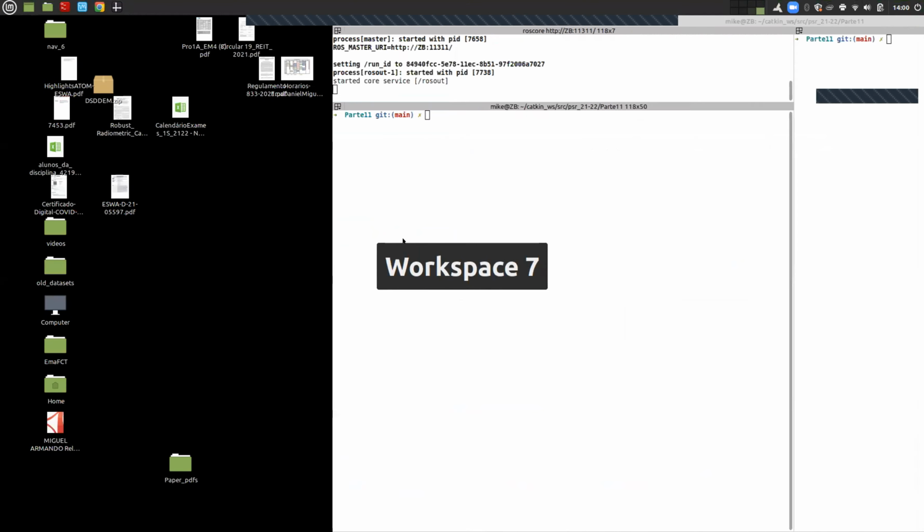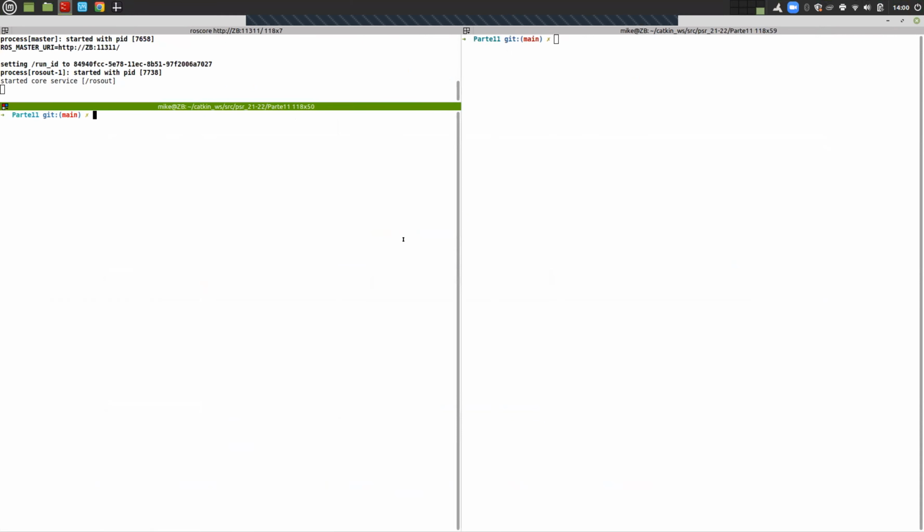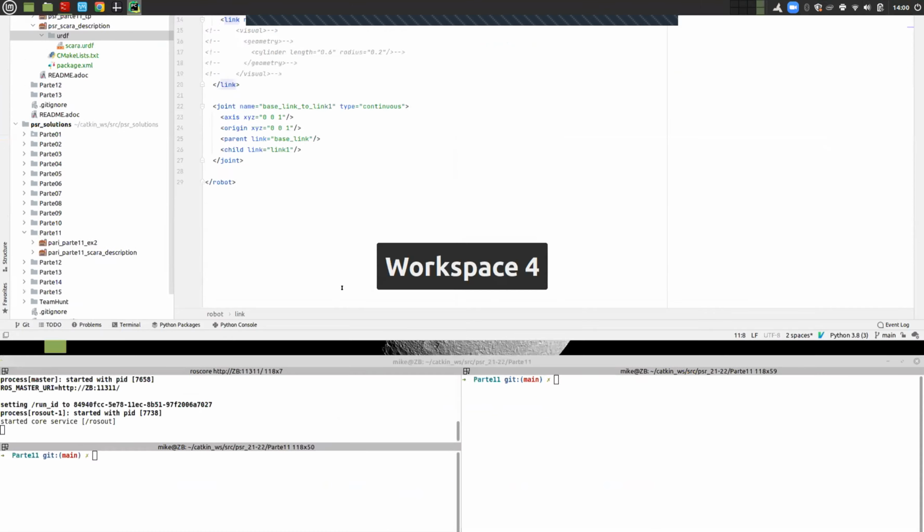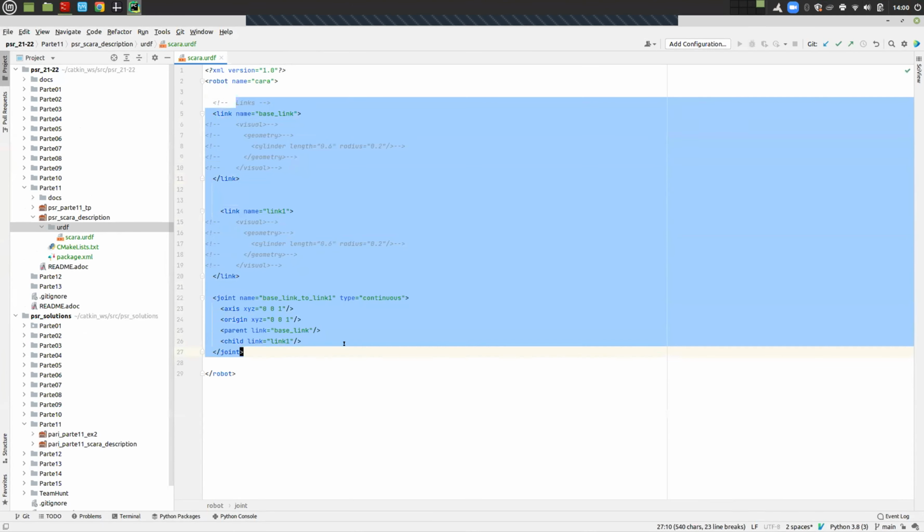Now robot state publisher, but the robot state publisher, as I told you, will require joint state messages, but also the description of the robot, because the direct kinematics depends on the configuration of the robot. So if it does a Denavit-Hartenberg chain, it needs to know what kind of configuration of the joints exist in order to do the computation of the direct kinematics. This is done by defining the URDF, okay? So what we are going to do is to put the URDF inside the ROS parameter, and this ROS parameter is the one which is automatically read by the robot state publisher.